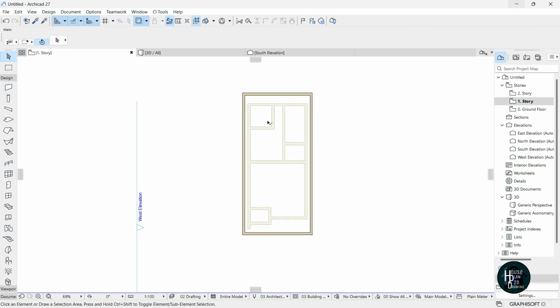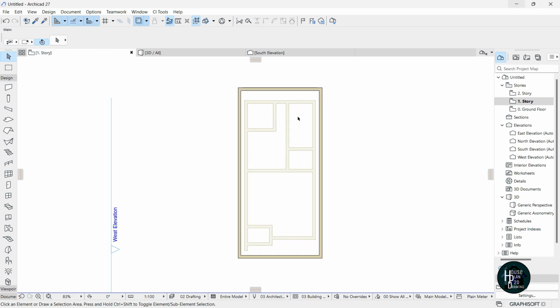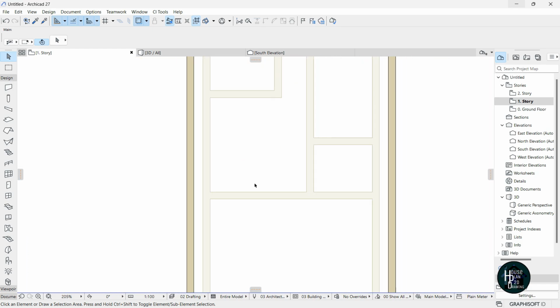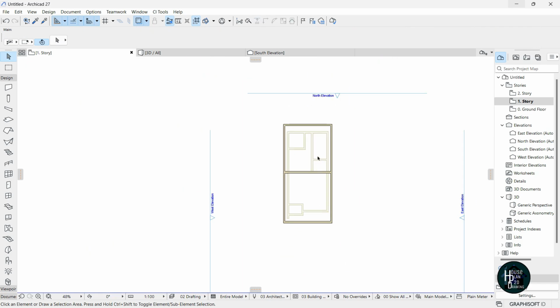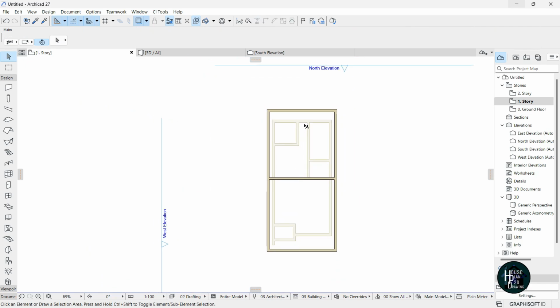Okay, once I've accomplished this, the next thing I'm going to do is start sketching out the design for the first floor. Okay, now there are some things that are constant in the drawing, as this particular wall here is constant in the drawing. So I'm just going to click on the wall tool here, click this edge here, stretch it like this, click this again. Okay, click this and click this side. Okay, so now it looks like the building has been divided into two.